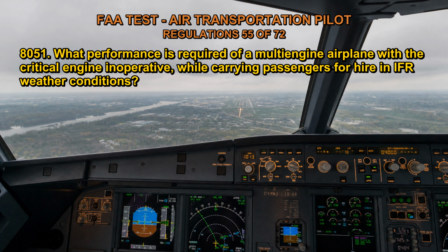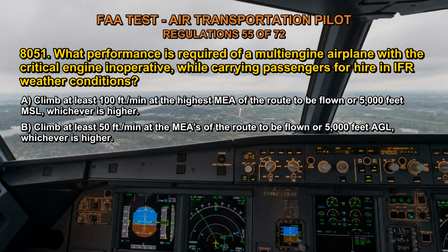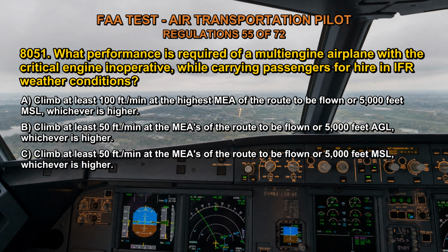8051. What performance is required of a multi-engine airplane with the critical engine inoperative while carrying passengers for hire in IFR weather conditions? A. Climb at least 100 feet per minute at the highest MEA of the route to be flown or 5,000 feet MSL, whichever is higher. B. Climb at least 50 feet per minute at the MEAs of the route to be flown or 5,000 feet AGL, whichever is higher. C. Climb at least 50 feet per minute at the MEAs of the route to be flown or 5,000 feet MSL, whichever is higher.